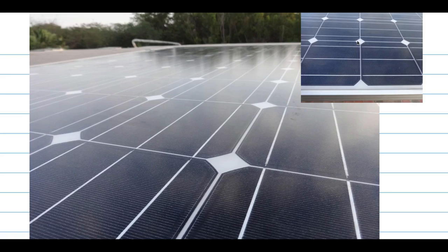Now all these areas are not effective area, and the solar insolation, even if it falls on this area, is not captured. Therefore, the entire module has a bigger area, accommodating all these gaps and spaces, as compared to the pure cell area alone. And therefore, the module efficiency is definitely going to be lower than the cell efficiency.